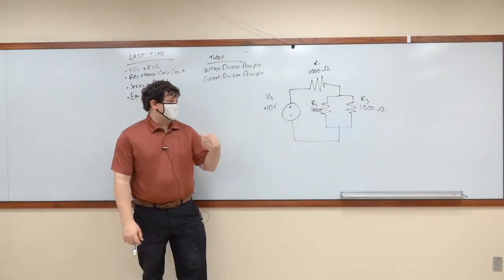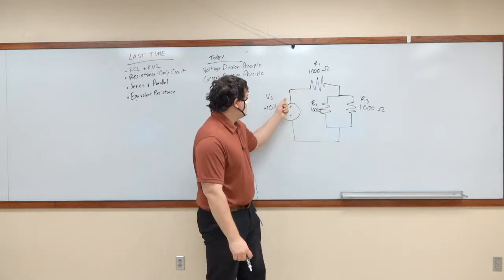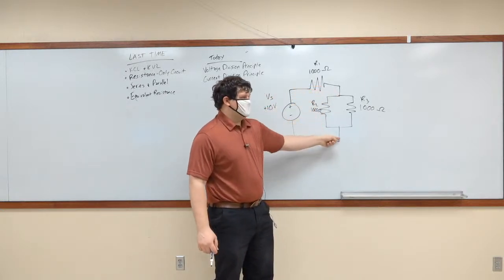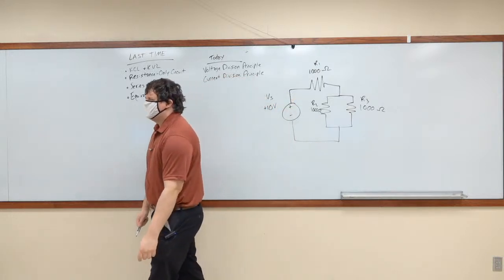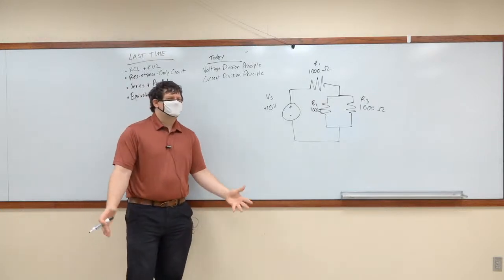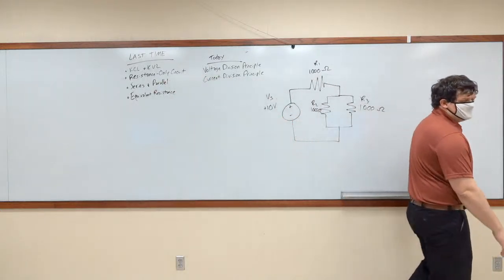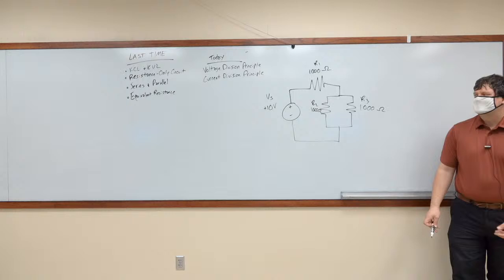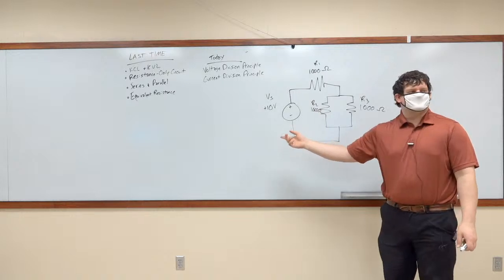Why? Because then what that means is if you had an electron that were to travel around the circuit, it would go up here, it would lose 10 volts, and then it would go down here, and then it would lose another 10 volts, and it would only gain 10 volts back by going through the battery. Which means once around the loop, it gets a negative 10 volt energy change. That's not accurate. It's unrealistic. It violates the principles of the conservation of energy. Once around the loop, it has to start at 0 and end at 0.